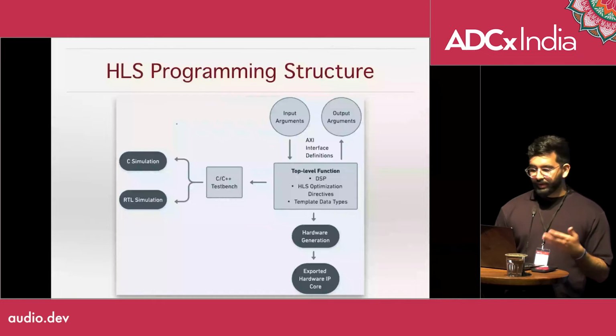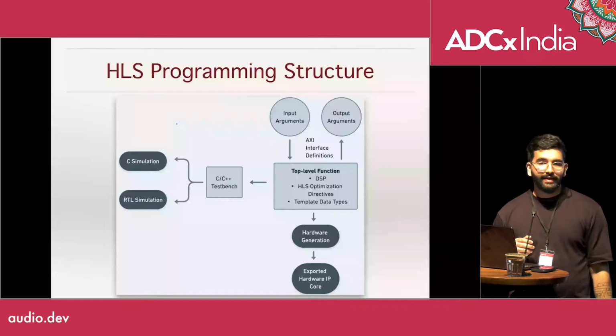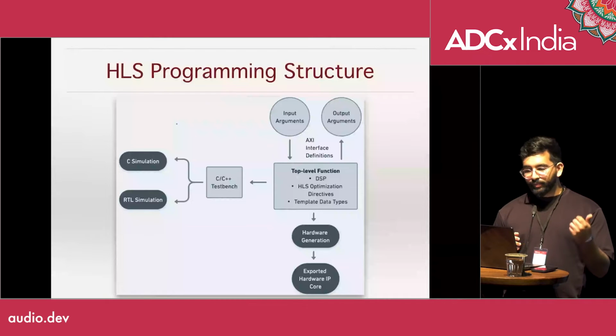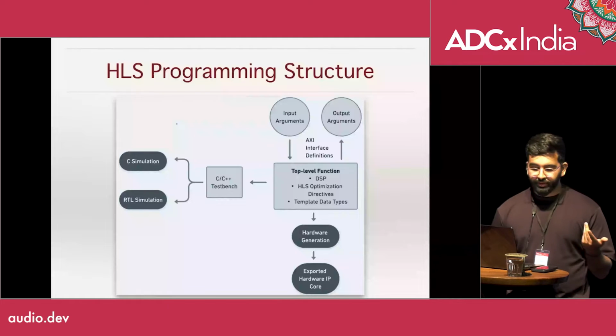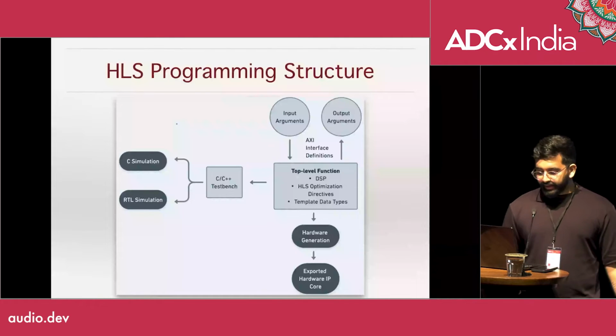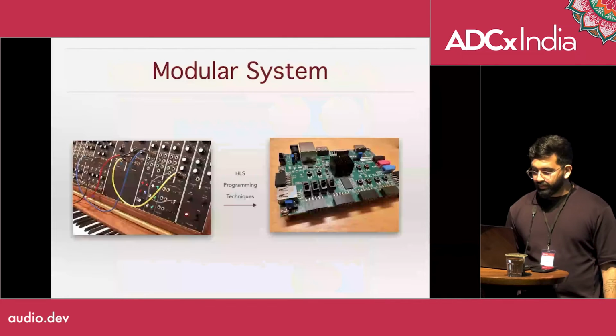And then we test the function within Vitis HLS with a test bench. You test the C function, but you also test the generated register transfer level, which is the generated hardware within Vitis HLS. With the same test bench, you can do that. And then you generate the hardware and export it into Vivado.